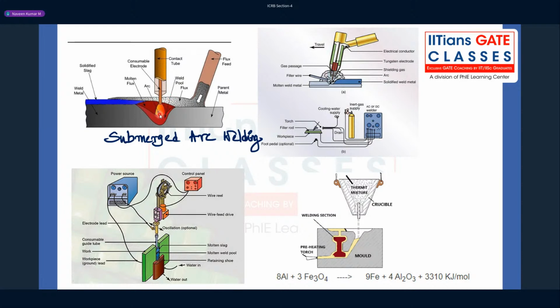So the arc is already submerged inside the flux, you cannot see the arc. That's why it's called submerged arc welding. See, this arc is submerged inside the flux, and as you proceed, the flux keeps on coming. As you proceed in the right side direction, this is the already welded part. And this submerged arc welding is used for joining pipes and ship hulls. Big heavy equipment, heavy thickness plates can be joined using this submerged arc welding.